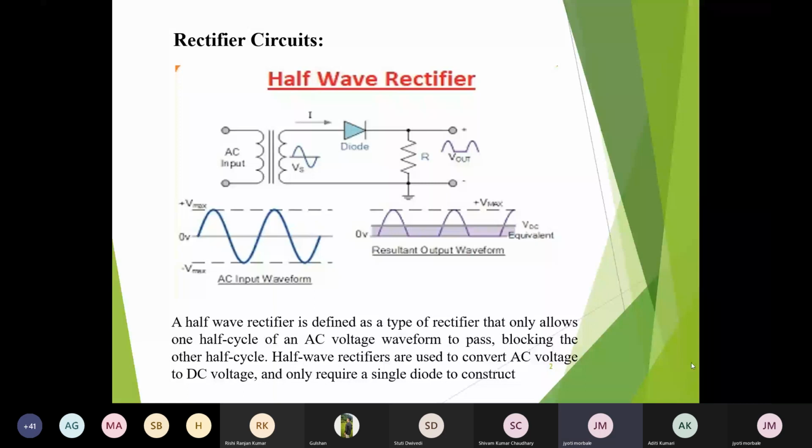So once again we are going to see the rectifier operation for the positive half cycle and negative half cycle. The rectifier is a circuit, as some of you have said, used to convert the AC signal into an equivalent DC signal. But as here we are talking about a half wave rectifier, faithful rectification will not happen here. That means whatever AC signal we apply at the input side does not convert 100% into DC. Some amount of unwanted factors are there at the output side.